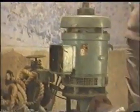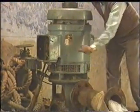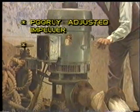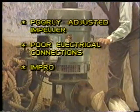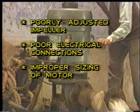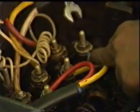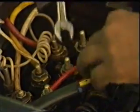Excessive heating of motor is usually due to overload conditions and consumption of excessive electric energy. It may be due to poorly adjusted impeller, poor electrical connections, improper sizing of motor, improper voltage, etc. These defects should be removed for proper operation of tube wells.